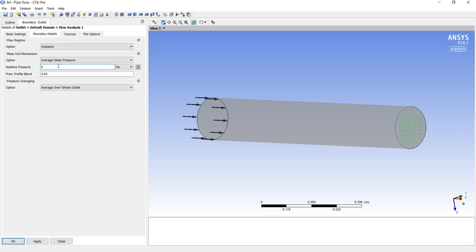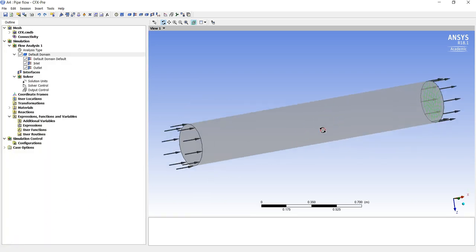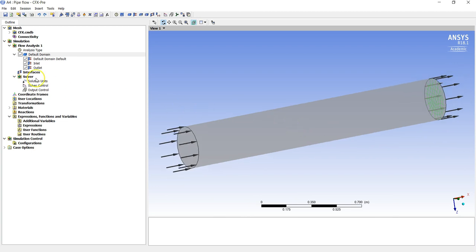And what that's basically saying is that there's no change in pressure across that domain interface. Or the reference pressure is 0 outside. In reality, that may not be true for this case, because we're going to have friction at the walls, which cause decreased pressure. But what this outlet condition does is it gives us a kind of blend value. So it gives us an approximate value of pressure rather than specifying it as exactly 0. So just clicking OK, you can now see that the flow is out of the domain. So the software tells us that.